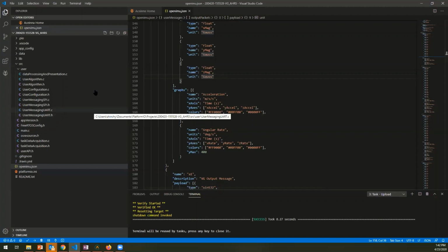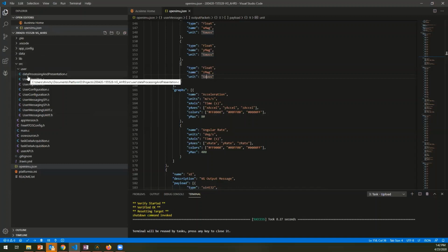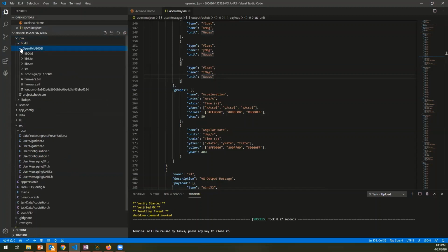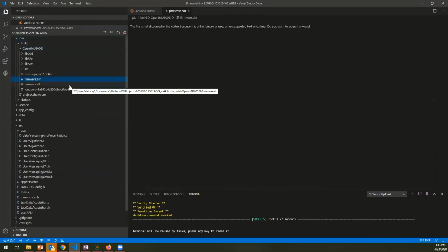One final section to point out is when we clicked the build button earlier and built this application, the binary itself can be found at the following location under .pio/build, and it's this file here, firmware.bin. You could save this and use the ST tools to write this to the part directly. And this is basically the same binary that is available in Navigation Studio in the code section.